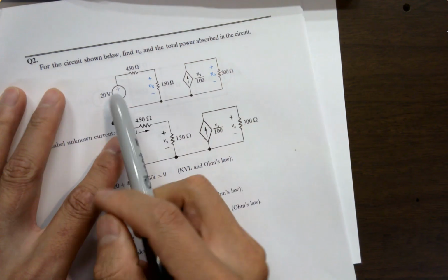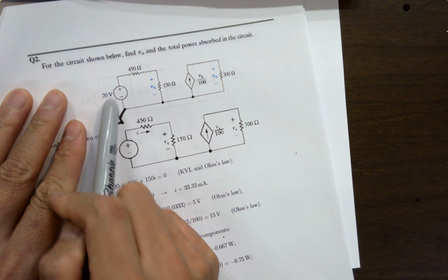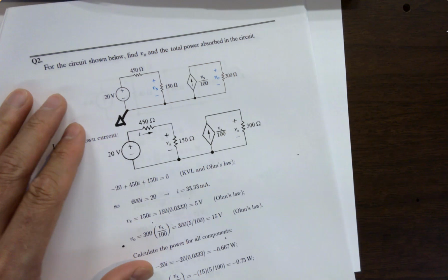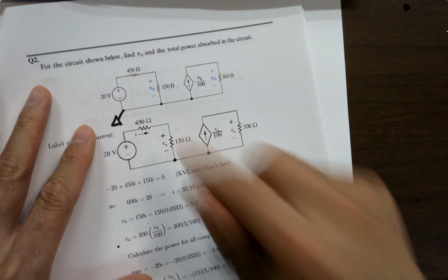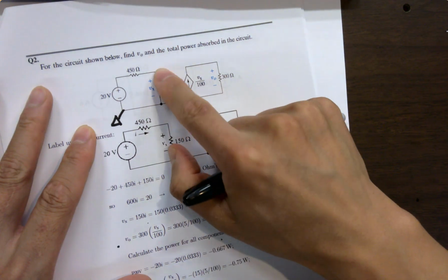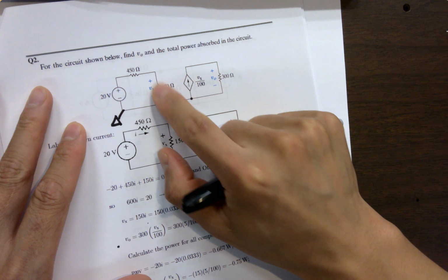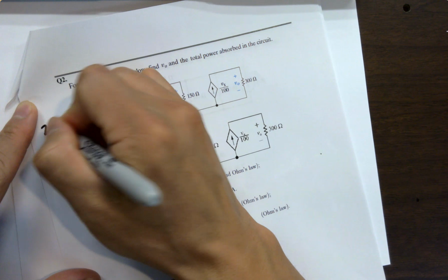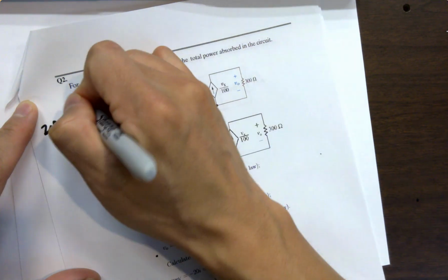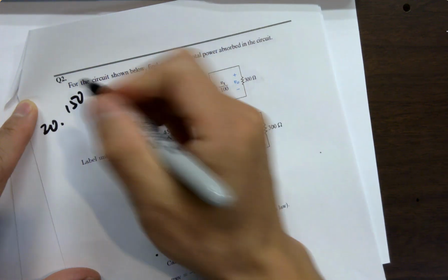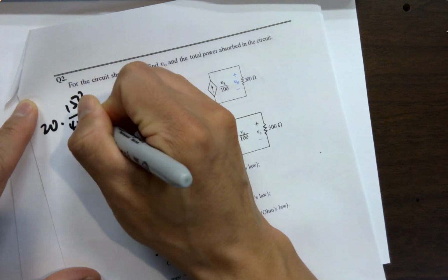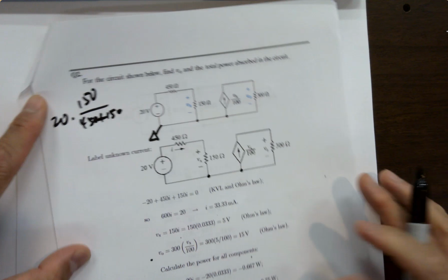So in that case, we have a DC voltage here. We got 2 resistors. It couldn't be easier. It's a physics 2 problem. Can you get a voltage here? Of course. How? A voltage divider, if you want: 20 volts times 150 ohms on the top over 450 plus 150. That's the voltage divider theory we have been using all the time.